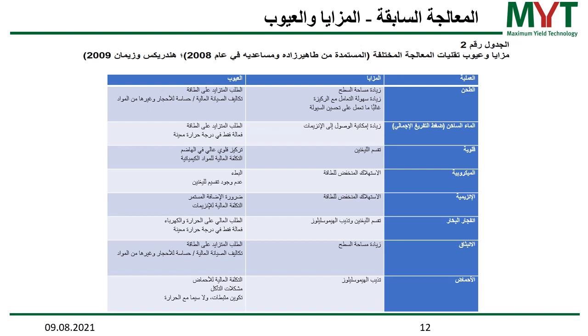However, you need a high alkali concentration in the digester to achieve that, or this leads to a high alkali concentration in the digester because you need to add a lot to actually have an effect. And this is high costs on chemicals. Not only this, you also have the chemical at the very end in the digestate and you bring it out to the land. So this is not a good way to go overall.